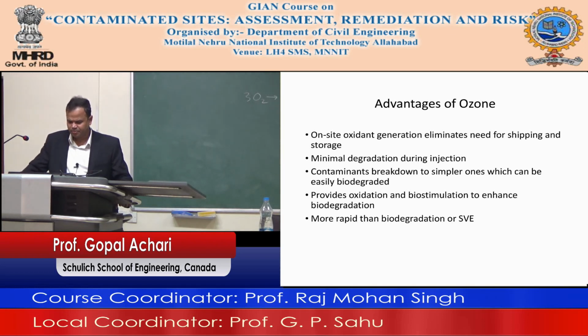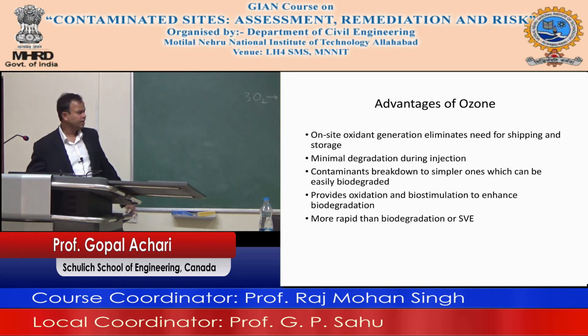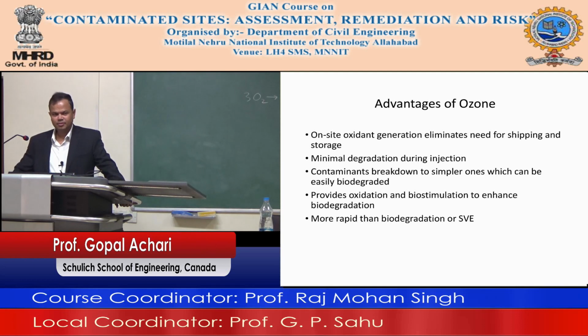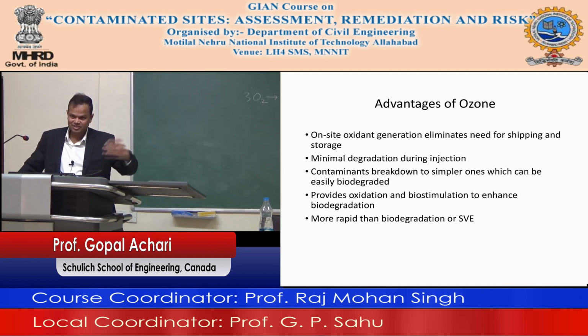Contaminants break down to simpler ones which can be easily biodegraded. It provides oxidation and biostimulation. The other thing about ozone is it breaks down to form oxygen. One of the things that ozone does is oxygenate the water. Once it breaks down, your dissolved oxygen concentration will increase.